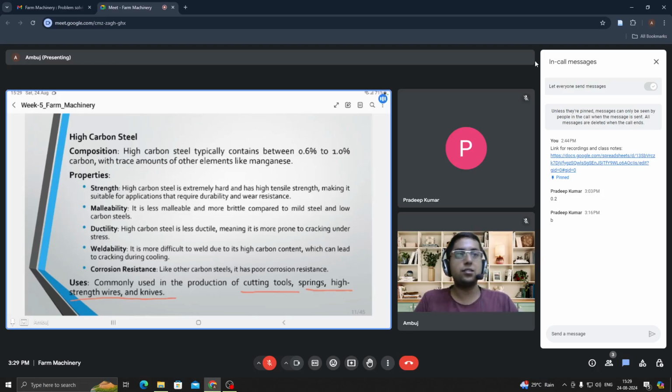In tractors, components like brakes, indicators, and switches are all tested for cyclic loading and unloading for at least 1 lakh cycles. So wherever the stress condition is higher as well as cutting is required, we often go for high carbon steel, because the hardness is very large.